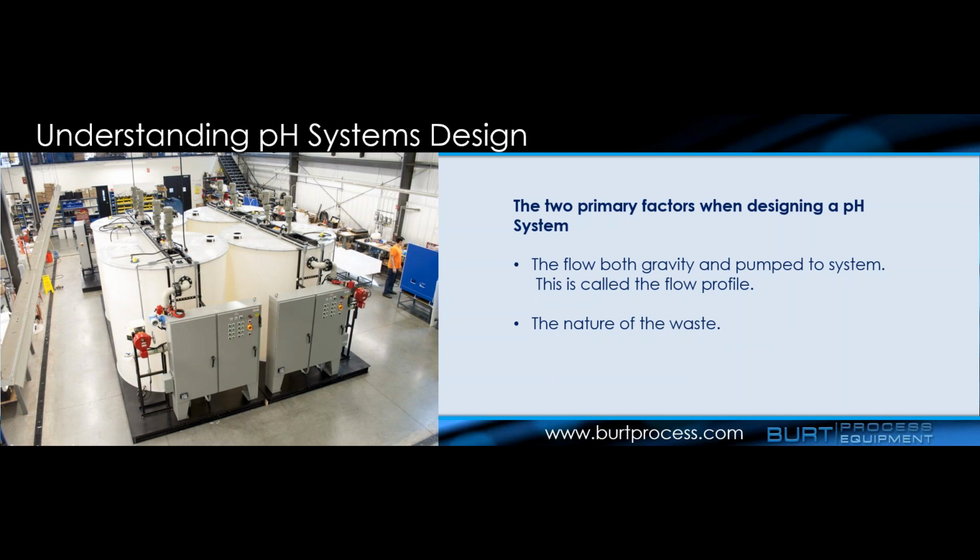So in doing pH system design, there are two primary factors that come into play. One is understanding the flow profile, both gravity and pumps, which is going to be transferring the wastewater to your system. We're not looking at wastewater that involves any kind of sanitary waste. We're talking about laboratory waste, clean process waste, high purity water waste, chemical washdown, blowdown, a lot of different things that need to be looked at or treated depending upon the municipality you're in, all contribute to this flow profile. Equally as important to the system design as the volume is the nature of the waste. What is the actual chemistry that's going into your system, or the actual waste product which you are trying to treat?